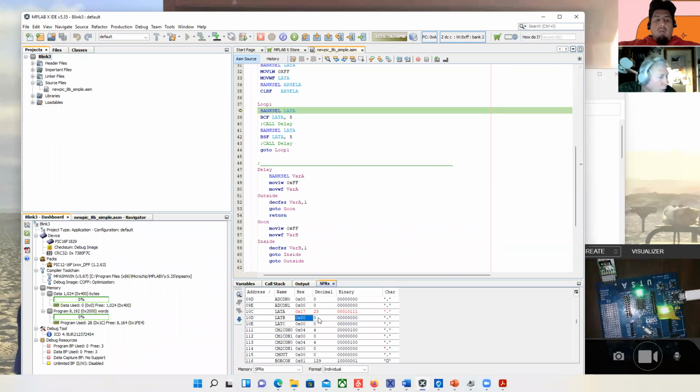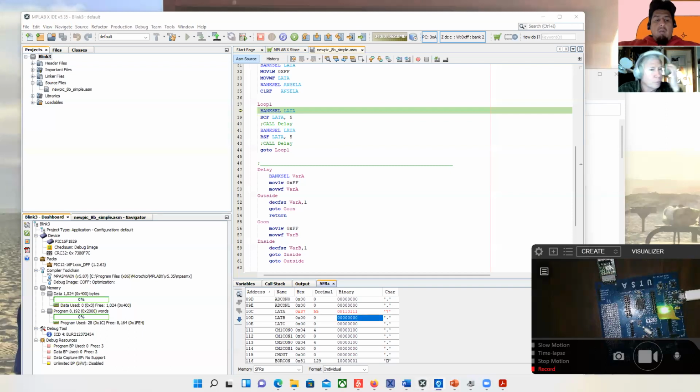So you can see when I change this bit right here, that 0, and I might be able to click on this one right there. And if I back this up and I make this a 1, and then I hit return, it should turn the light off. Yeah, and it does. So I made this bit 5 a 1, which now makes the LED go off because again, it's a common anode LED. So my individual cathodes have to be set to 0 to turn it on and 1 to turn it off. All right, let me stop with that. What questions did you have? And we'll quit.